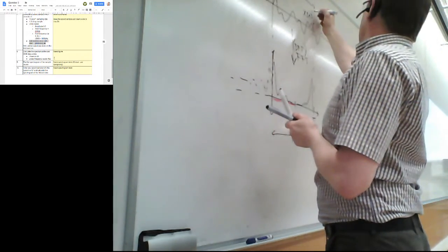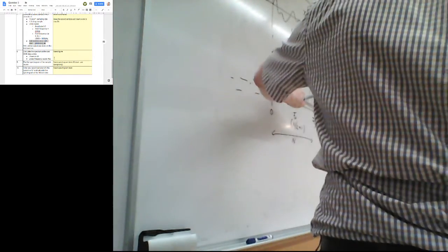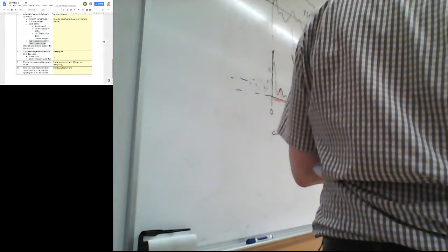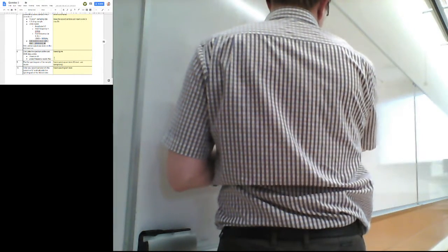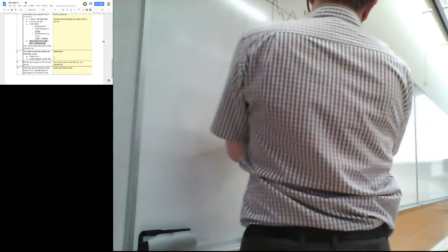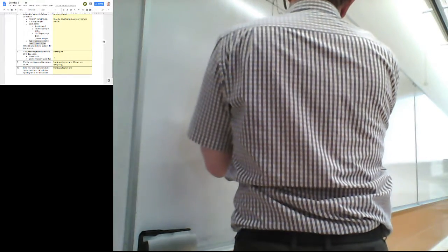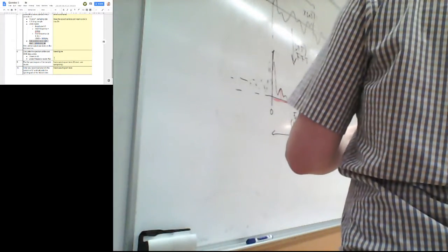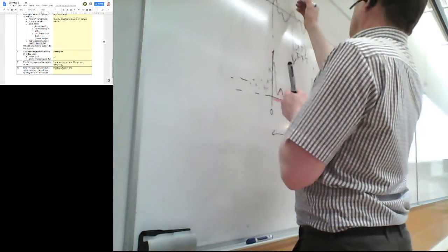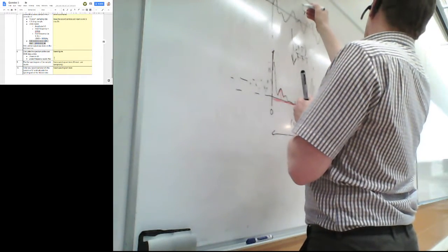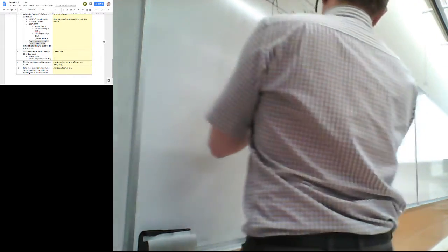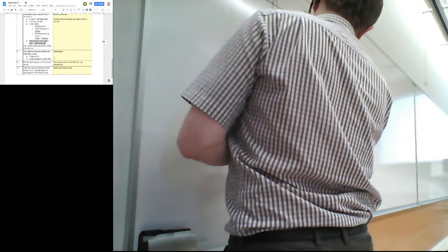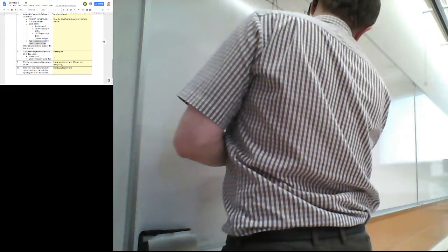This gives you some trouble if you want to see very fine details on the spectrum between some of the more intensive peaks. In that case you would use some smoother windowing, which gives you a flatter spectrum, but it goes deeper on those values.